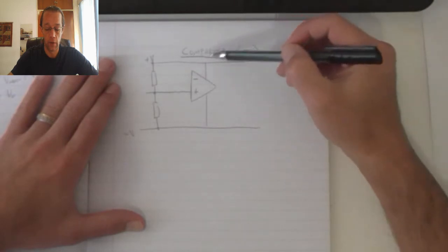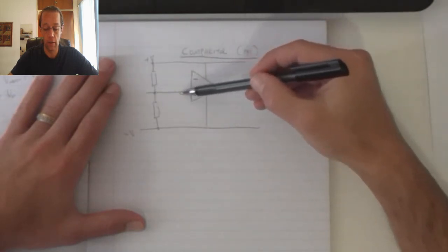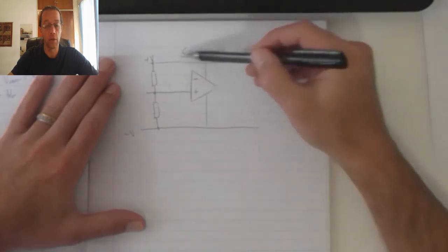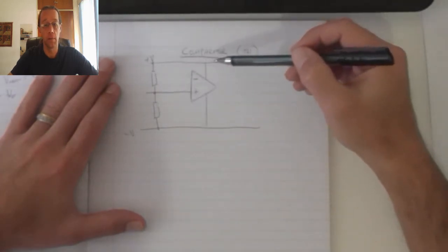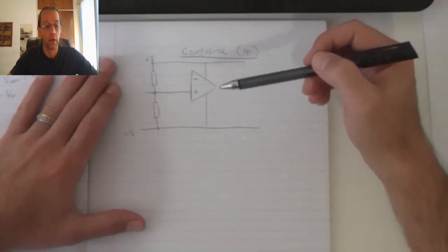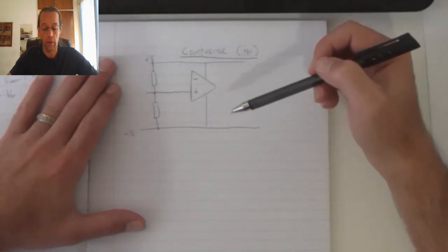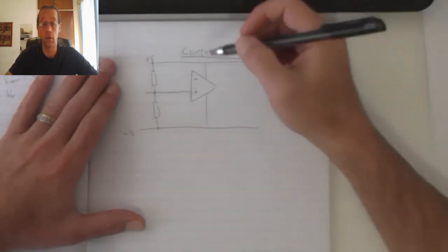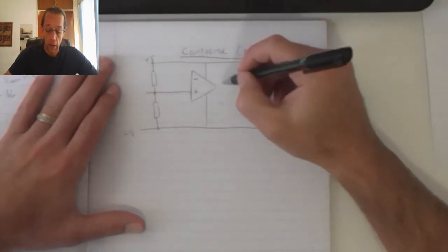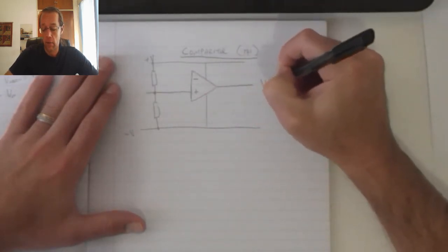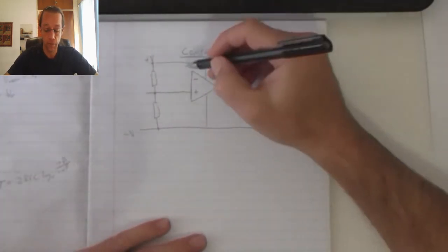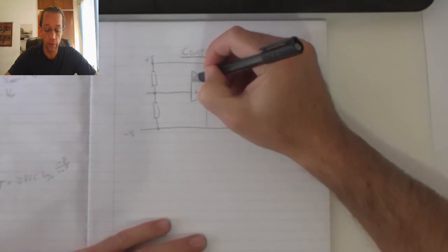The comparator is going to have a reference voltage caused by a voltage divider circuit that's connected between the supply voltage. We've all seen this type of circuit configuration, or the effects of this circuit configuration, in devices like automatic light switches and automatic wipers. The output is going to connect to a device or memory element, and then my input over here, this is my actual input.